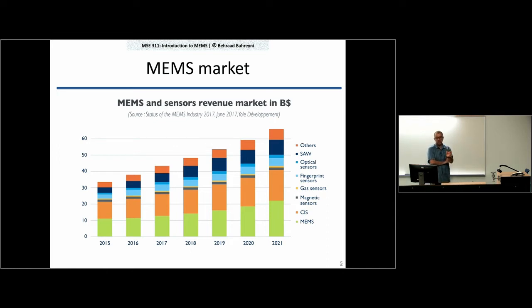And there is such a tight restriction on bandwidth usage that you basically have to optimize the amount of frequency band that is available to you, so that basically you pass more information, more data, more customers. And for that reason, we are seeing more and more RF MEMS components deployed. These are actually more than 10 per mobile device nowadays.